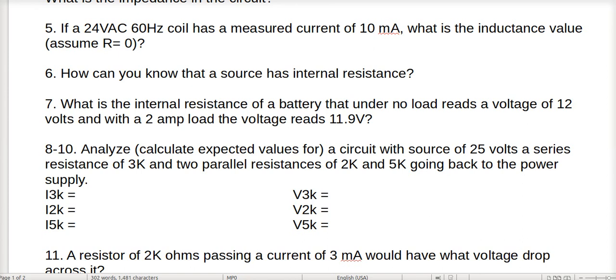So the impedance is what's limiting the current when you start getting into inductive circuits, and that impedance can be found, if you will. We're assuming R is 0, so all you have to do is work back out using the 2 pi FL equation equals XL.